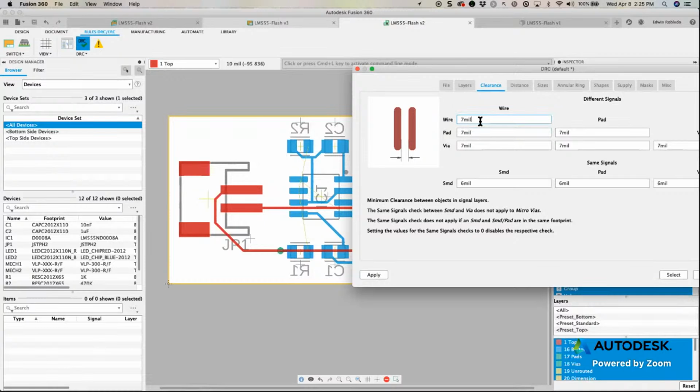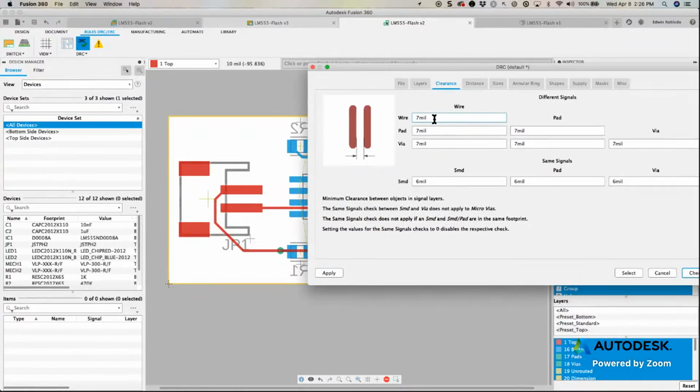That is the distance. And in this case, I was using 7 mils, but usually you may use 6 mils if you have a denser board. You could go lower. You got to be careful with going too low, because then it could create a whole new kind of problems on the board. Also, it may just not be manufacturable.